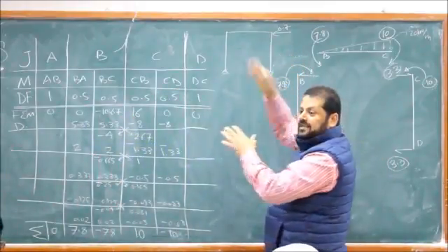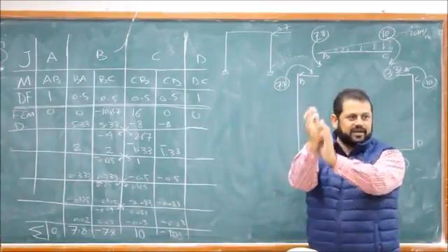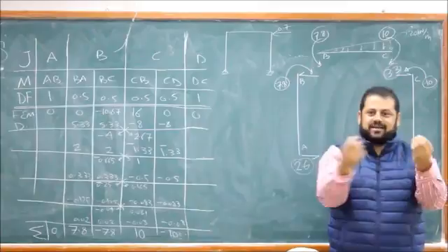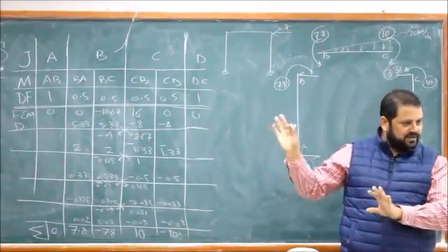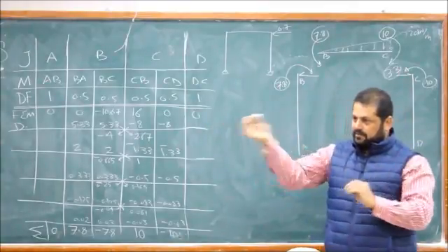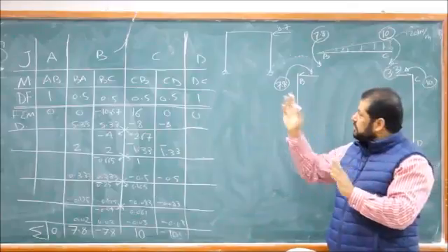Good? Now this is not the most difficult thing. This is easy. We know. We put a support, so we got a reaction. We want to remove the support that does not exist, so we put the opposite reaction and solve. We know this. We apply an opposite reaction with the same magnitude. Okay.